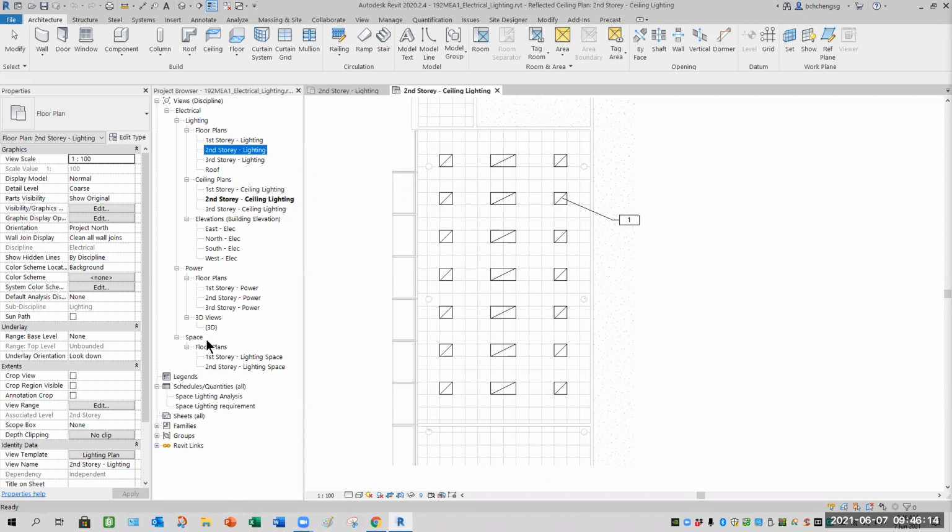But if you are doing more towards construction, that means next time when the model is done, or at the end of the day you need to do it for the construction site, then you must add the plenum level inside, because you might need to lay the conduit.